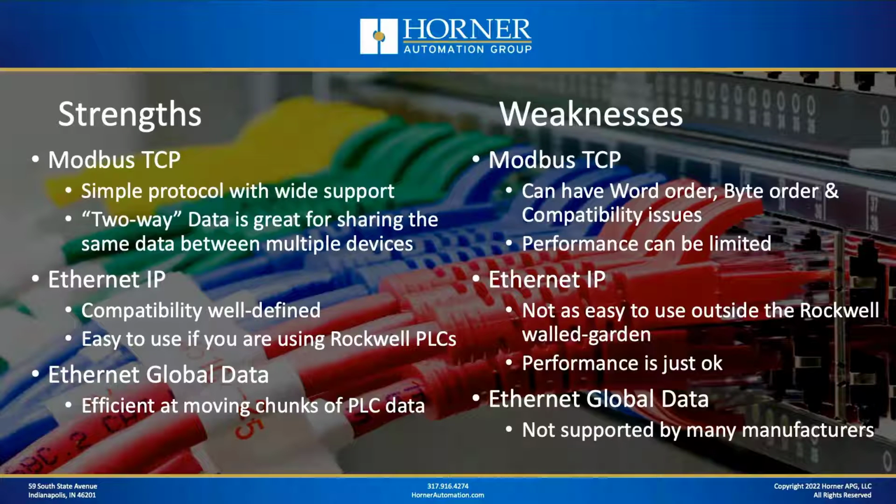Now, disadvantage. Because Modbus was created in the days really before 32-bit data types were prevalent, like floating point, etc., you can have word order or byte order compatibility issues. In other words, some manufacturers may not really follow the best practices in terms of the order in which data gets sent out over the wire, and it's possible for words or bytes to become switched. Now, it's not super normal, but it does happen way more than other protocols. So that's something to be aware of.